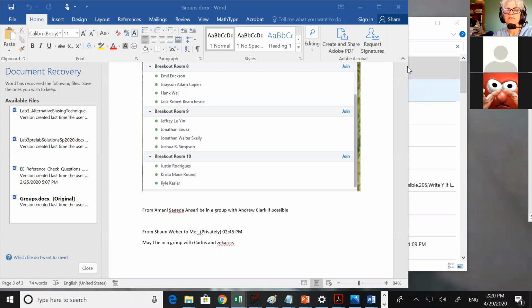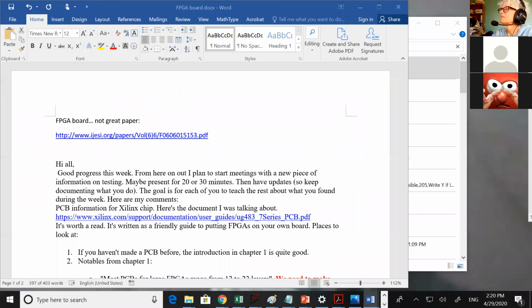Those are 2 specs. The other specification is that the supply voltage is 5 volts, but the input voltage to your common collector at rest is 3 volts. So you want to design for a V in of 3 volts.